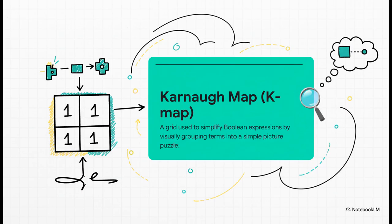So what is it really? A K-map is basically just a grid of squares, where every single square represents one possible combination of your inputs. You take your function, and for every combination that makes it true, you put a 1 in its box. And just like that, you've created a picture of that super complex expression.